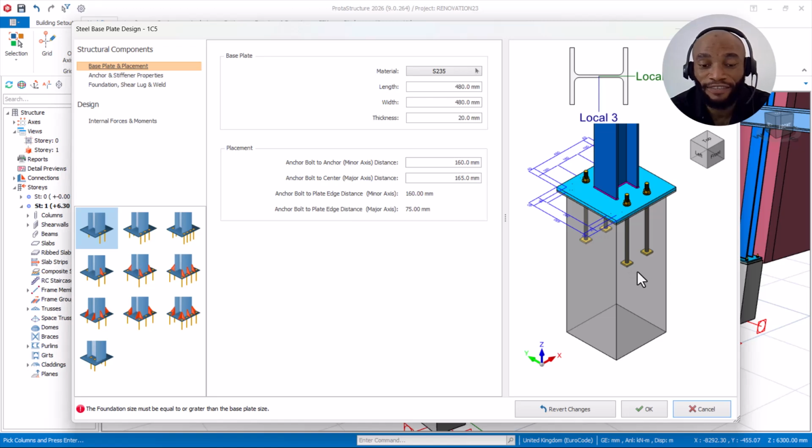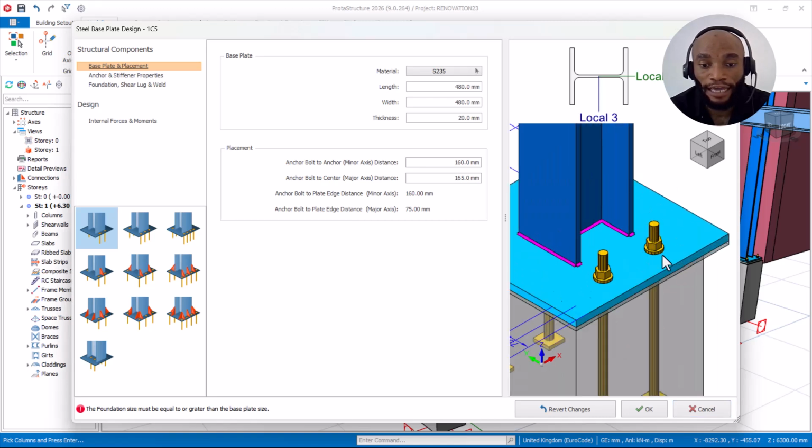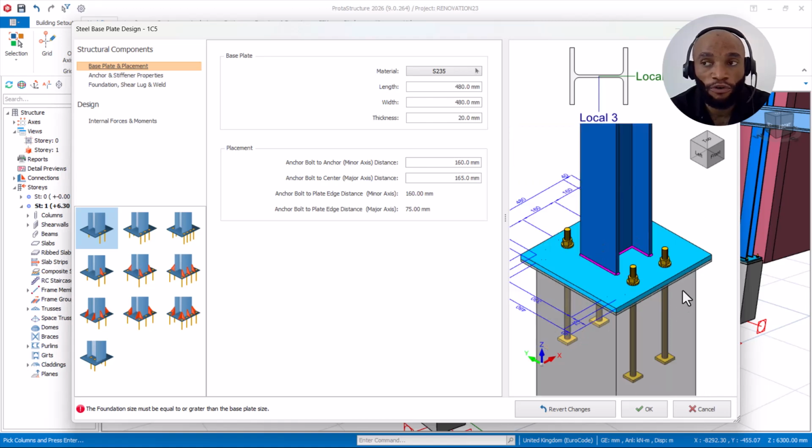So in this case, my pedestal is 400 by 400 based on this design, and my stanchion is HEB 180. The height of the stanchion, or of the whole building, is 6.5 meters high, which you can see around this place. Okay, no, 6.3 meters high, correct, 6.3 meters high.